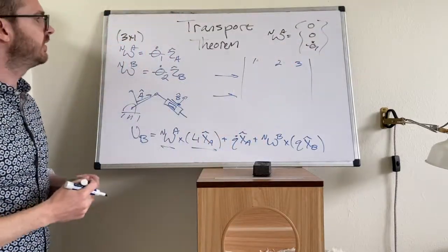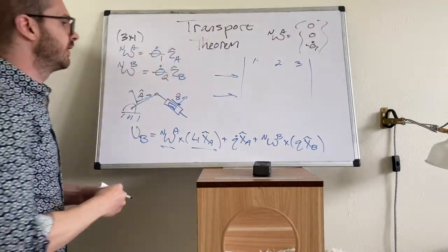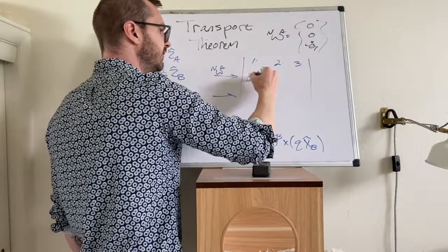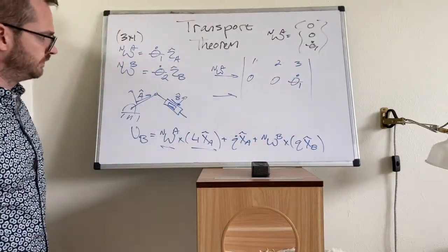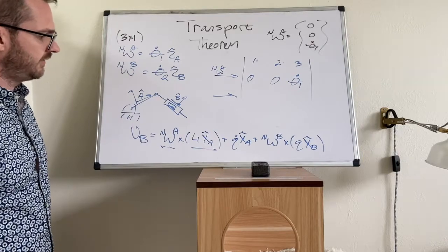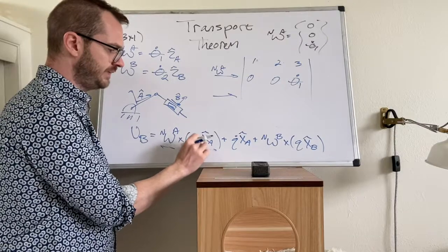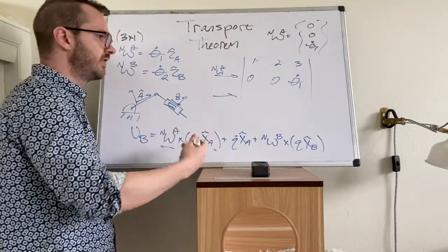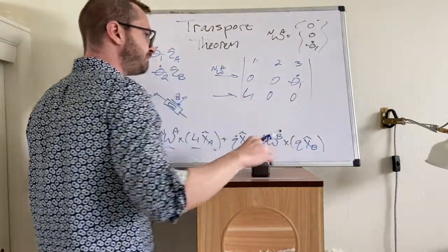So it's a theta 1 dot in the Z direction, and there's nothing in the X and Y's. So I'm going to take omega into A, I'm going to put it right here, and it's 0, 0, theta 1 dot, and then we take the position vector. The position vector is L1 in the X hat A direction, and then it's 0 in the Y and 0 in the Z. So L1, 0, 0.